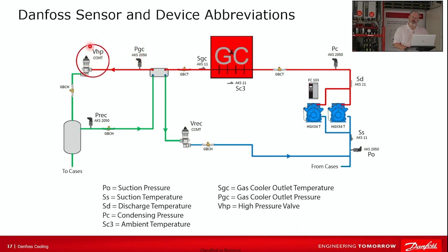Now we have a new one, the V for valve high pressure. A pressure for the receiver. And then the valve for the receiver. So the uppercase letter, and this is all through our software and various controllers: P represents a pressure transducer, then the descriptor. S represents a temperature sensor, then the descriptor. And then the same for the V for valve.